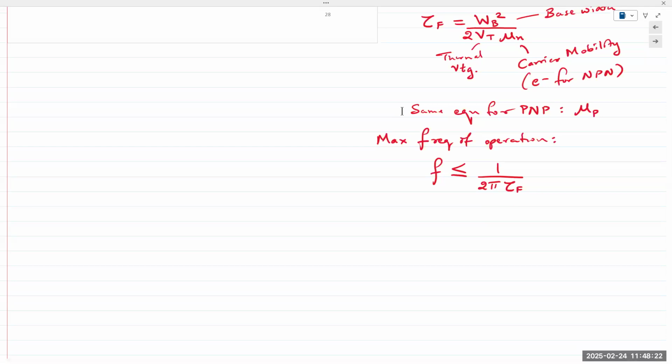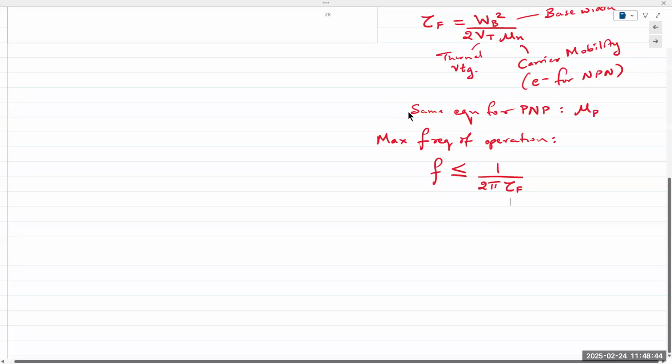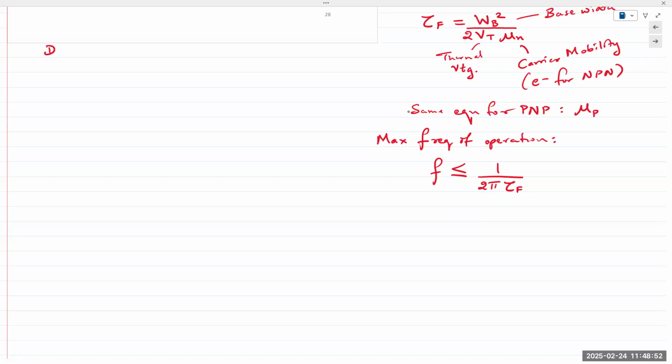All right, so charge carriers are going from the emitter to the base. The base stores the charge, which is then injected or moved into the collector, right? And then we have current flowing through the BJT. So this charge that is stored in there gives rise to a capacitance between the junctions, and this capacitance is known as the diffusion capacitance. Okay, diffusion capacitance.